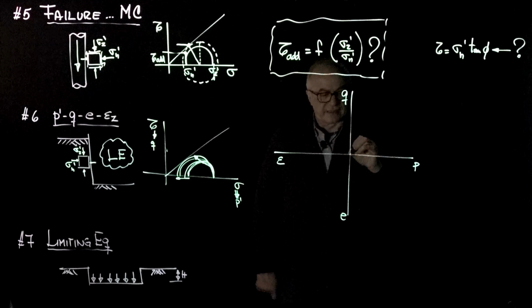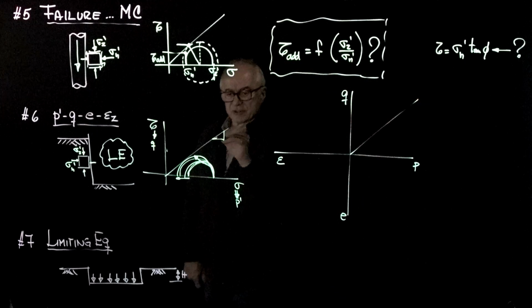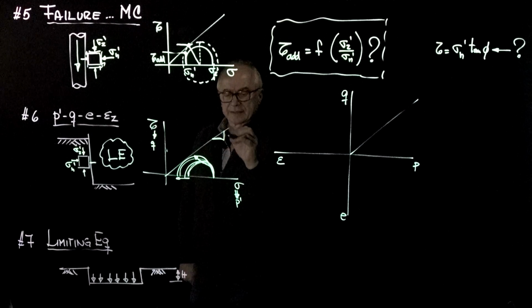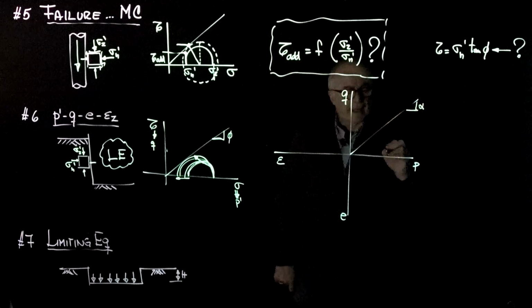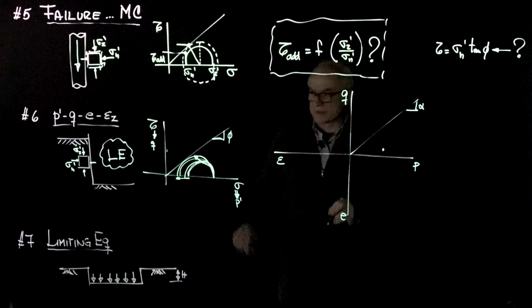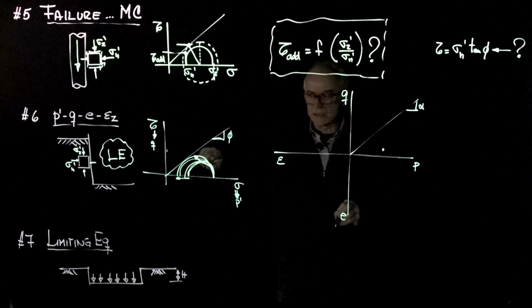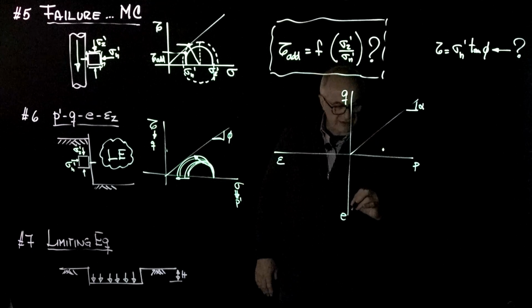Now this is the alpha line. This is not the phi line. This is friction, but we have converted tangent alpha equals sine phi. This is the alpha line. And so we start with some stress anisotropy because there was an initial Mohr circle, and we're going to evolve at 45-degree angles, but let's complete the plot.